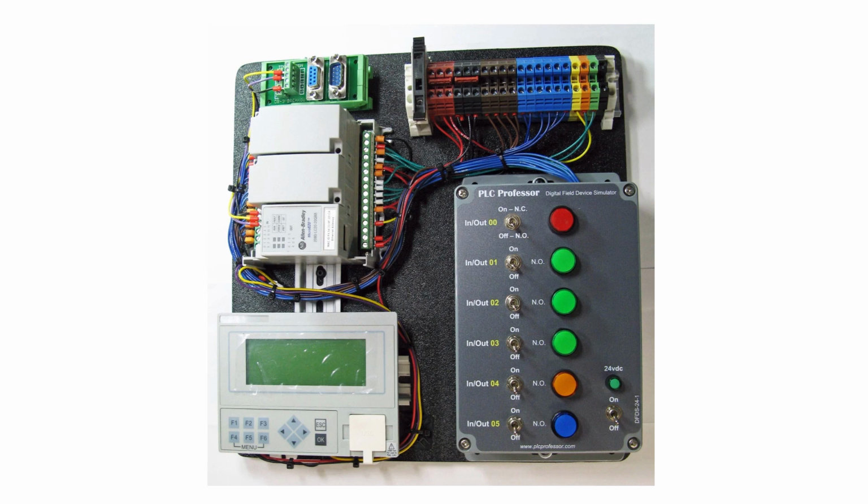So right behind that white rubber cover, if you pop it off, is the USB. You plug into that, plug into your laptop, and if you've hooked up the 3 communication wires up to ground, transmit, receive on the 820, now that's your serial RS-232 USB connection between your laptop and the controller. But you still got the Ethernet. As long as you've got Ethernet, I can't imagine using the 232 unless you want to use that display.